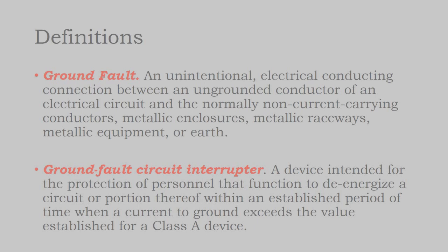It's a high voltage power line. And then it connects to that non-current carrying metal conductor. And it faults. And that current connects to ground. And that might sound like, oh no, there's something wrong. And there is. A ground fault that is not planned for nor expected is not a good thing. But what would be worse is for that ground fault not to occur and for that metal box or that metal conduit on the building to be energized, and you go up and touch it and you become the ground path. And that's even worse.